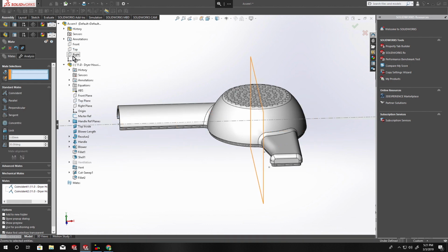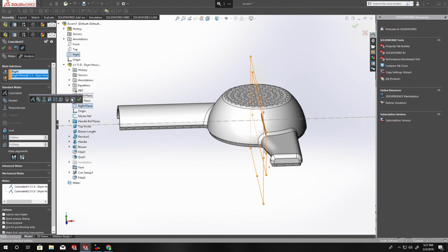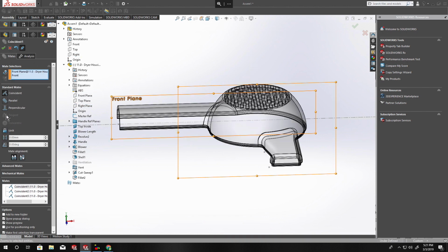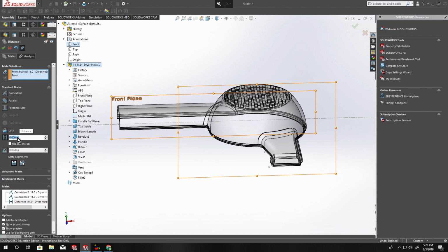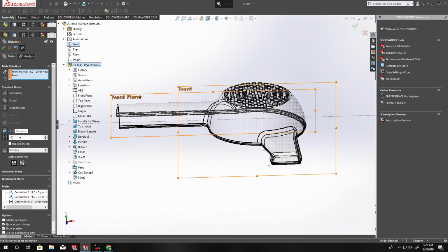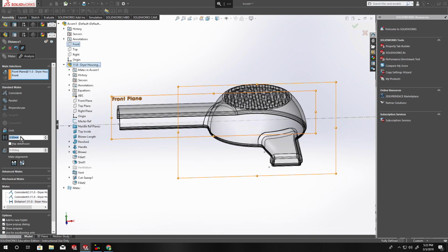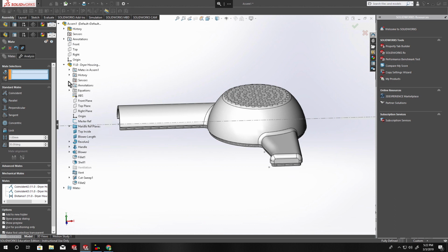Good. And right to right. And that's good. Now if I ever want to go and change some of these constraints, all I'd have to do is click on this distance or change what kind of constraints it was, but probably more often than not a distance, and I could make it 10. Now that moves at 10. It's a lot more versatile than just leaving it as fixed. So check mark on that. So that one's in there good.